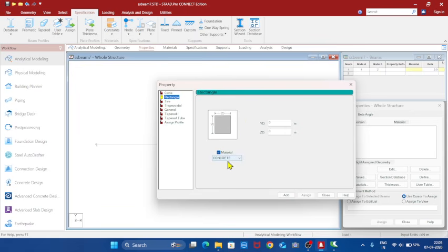The material by default is concrete. You can change the material if you want any material. So let it be concrete here. So depth, the depth of the beam. We need to assume 1/10 of the span as trial depth. So 1/10 means, say, let me take 0.45 as the depth and 0.23 as the width.